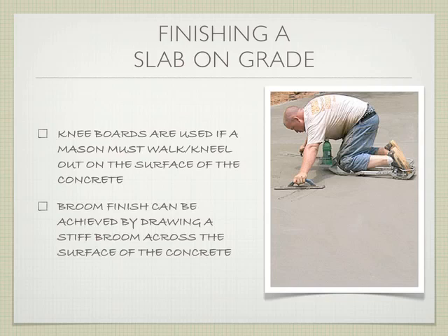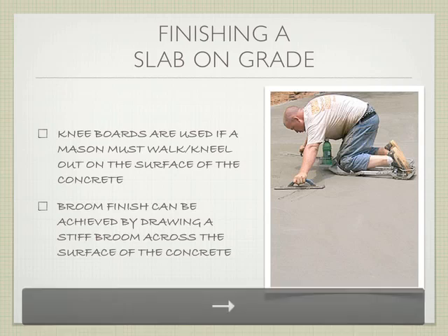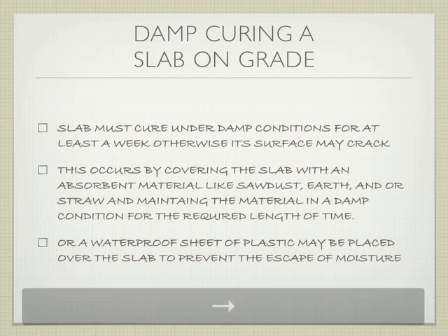But if you were to spread out your weight on a larger surface area, you can actually get out on the concrete and work on it. So if you'd rather do a broom finish or something like that, this would be the time to do the broom finish. You go out on your knee boards and you do the broom finish on the concrete. And so this is a pretty sweet setup. He's got his drink with him and everything, and he's out there doing his thing. Obviously, this is the more professional solution to it.